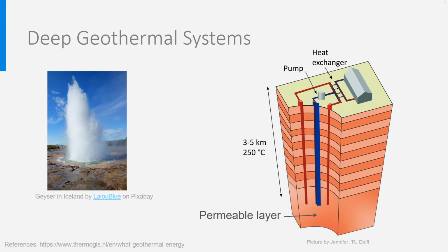In systems like the dry rock enhanced geothermal system that we have shown on the picture, only 1 pump is needed in the injection well. The pressure in the Earth core is much higher than the atmospheric one. In the extraction wells, no pump is needed. Such geothermal systems can provide water at 40 to 70 degrees like in the Netherlands, but also at much higher temperatures like in Iceland or Switzerland and many other places all over the world. When the temperature is above 100 degrees Celsius, it is even possible to use the steam to produce electricity, which will be treated in another lecture.